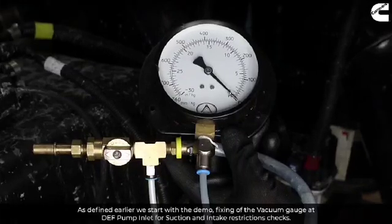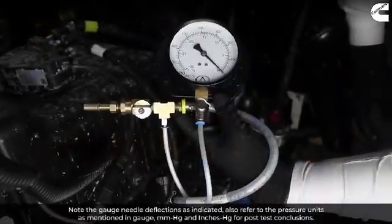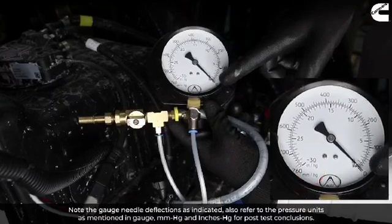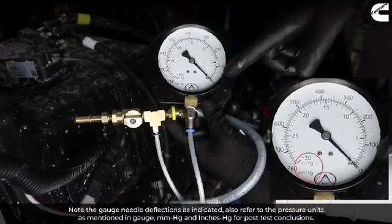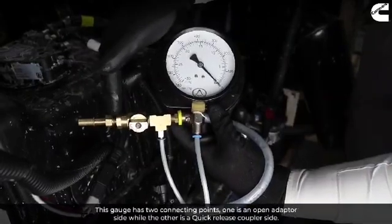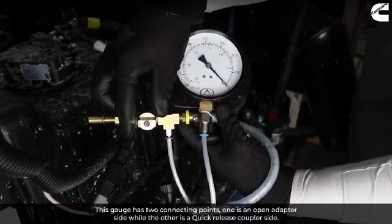As defined earlier, we start with the demo, fixing of the vacuum gauge at the DEF pump inlet, for suction and intake restriction checks. Note the gauge needle deflections, as indicated. Also refer to the pressure units mentioned in the gauge, mmHg and inches Hg, for post-test conclusions. This gauge has two connecting points, one is an open adapter side, while the other is a quick release coupler side.